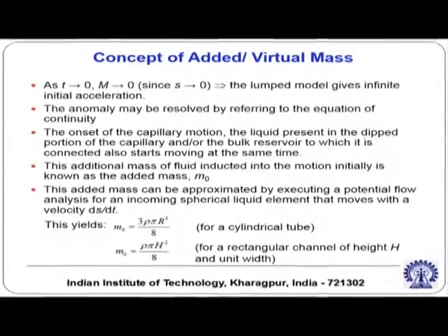The first point which we would like to address is the infinite initial acceleration issue, and how that can be corrected. That can be resolved by referring to the equation of continuity. Look at this description: at the onset of the capillary motion, the liquid present in the dipped portion of the capillary or the bulk reservoir to which it is connected also starts moving at the same time, right.